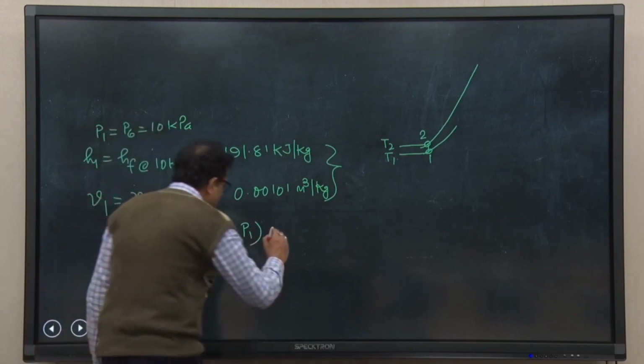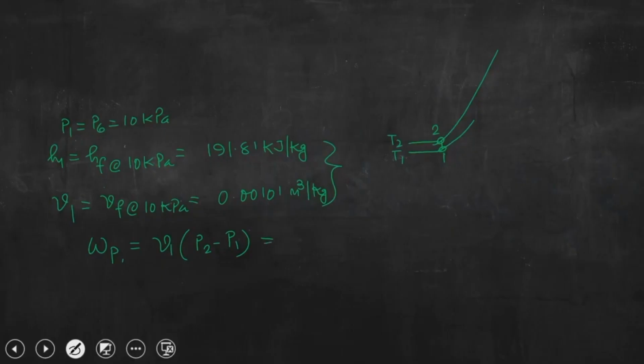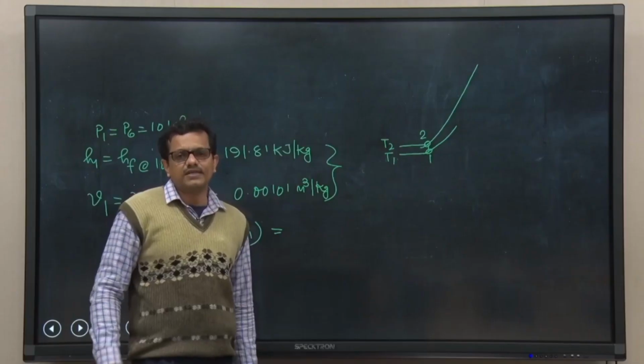It is not a PdV work. For any process, be it reversible adiabatic or reversible isothermal, the steady state steady flow work done is minus VdP.